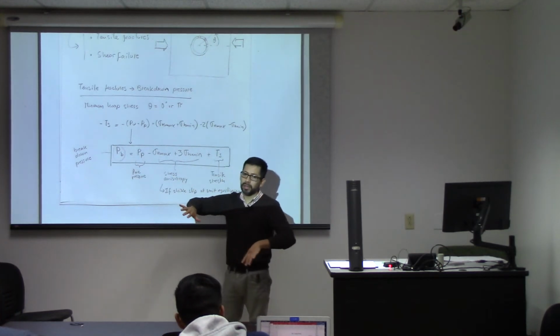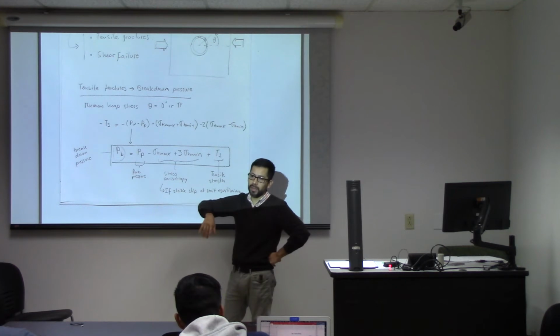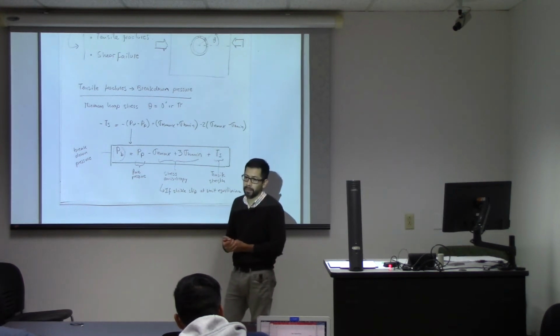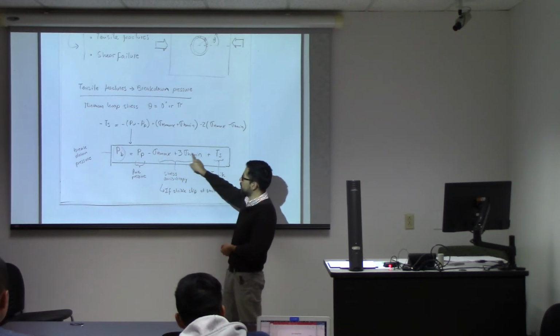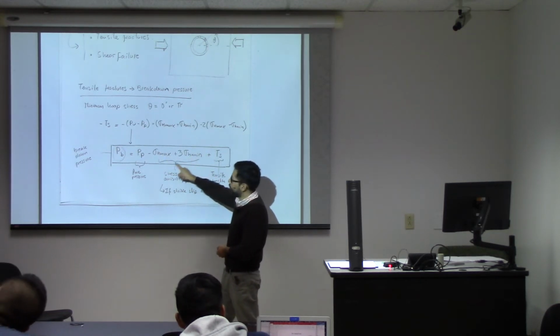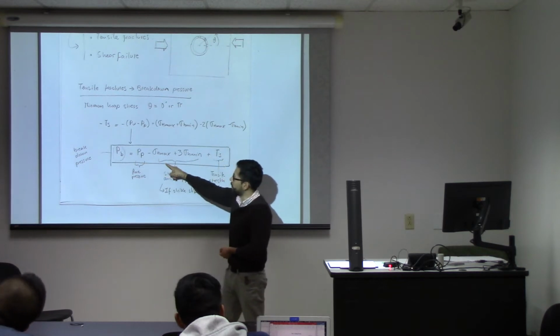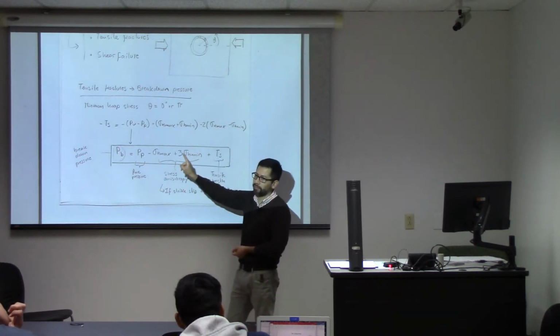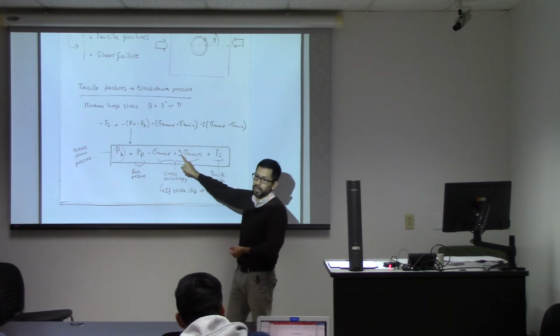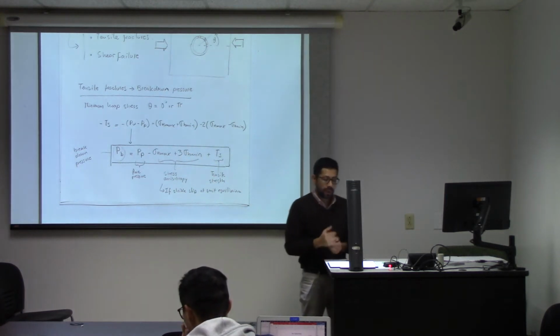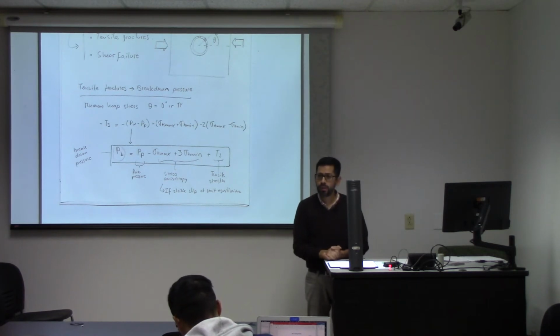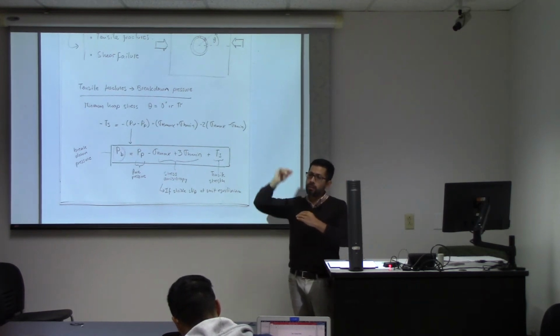For example, let's assume that we have stresses in horizontal direction, they're all the same. So here you can see that if this one is more or less equal to this one, then the contribution to PV of the stress anisotropy is going to be 2 times the effective horizontal stress, which is going to help to get to a higher pressure. So basically this breakdown pressure tells you what is the maximum value in which you can get in the pressure in the wellbore without causing tensile fractures.